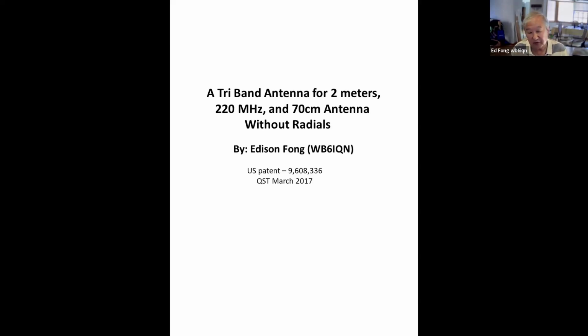So I give a whole series of talks, not all on antennas, and some on radios, history of radios, and basically a lot of these are my lectures for my graduate classes that we made more tailored for ham. A very popular one is IQ generation of single sideband. Conventional hams have these expensive Collins filters, crystal filters, and things like that. But these days, with an SDR radio, you don't do it that way anymore. That's why you can do it so cheap. You do it with I and Q. So I give a lecture on that.